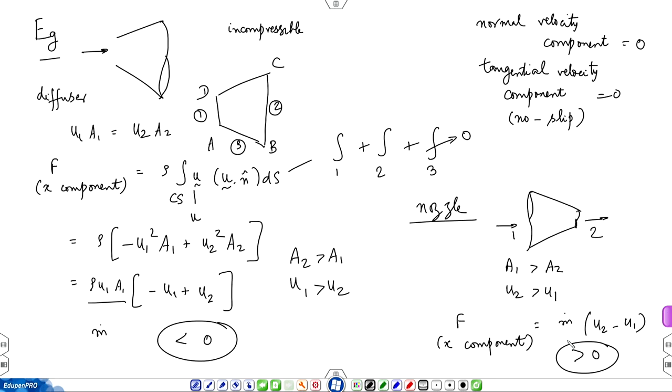So, these are technical terms which you might have heard earlier, but now you are seeing them in a formal setting. In this case it is useful to have that force. In case of a diffuser, there is an unbalanced force, so you need a separate structure to hold the diffuser in place. Okay. So, depending on the device being studied, the consequence of having either a zero force or a non-zero force would be distinct. In some cases it is parasitic, in some cases it is useful.